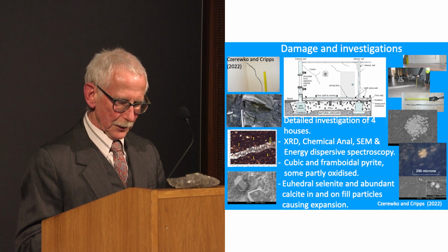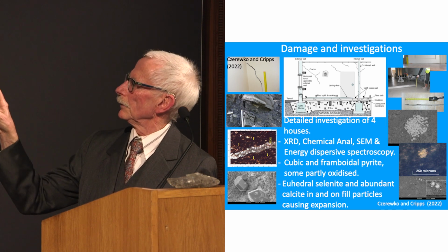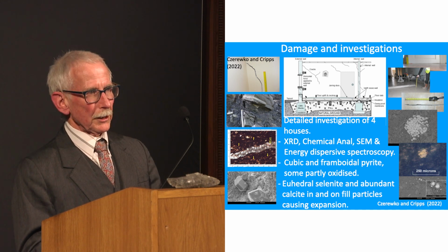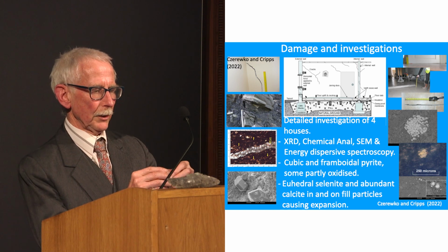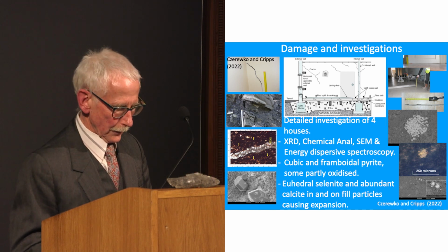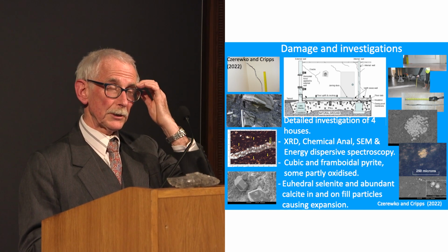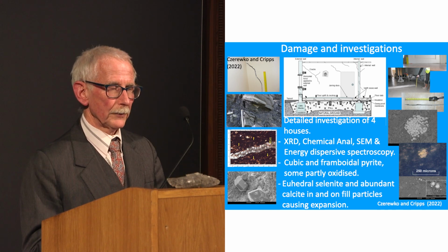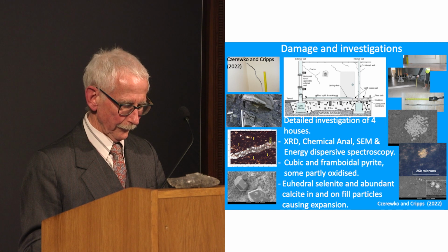There's also evidence of selenite being formed in these fill particles. This one here, these are the selenite crystals. Selenite is quite a soft mineral. Please be careful if you handle these later, but you can scratch it with your thumbnail. So it's unlikely that the selenite was present in the material before it was placed as fill, because otherwise, if it was present before, the crystals would have been crushed during the compaction of the fill to form the foundation.